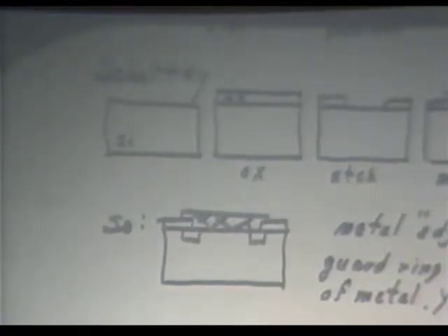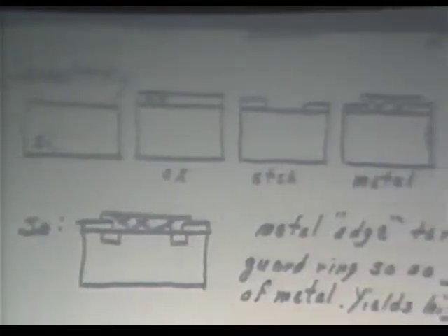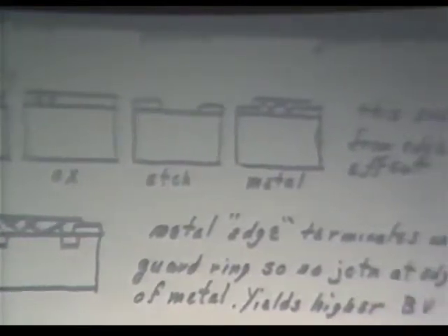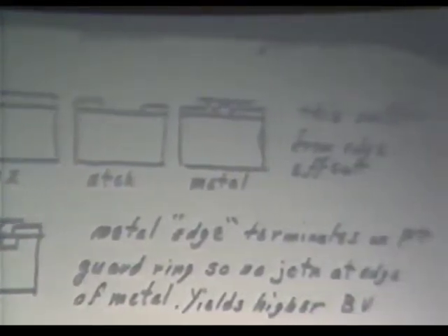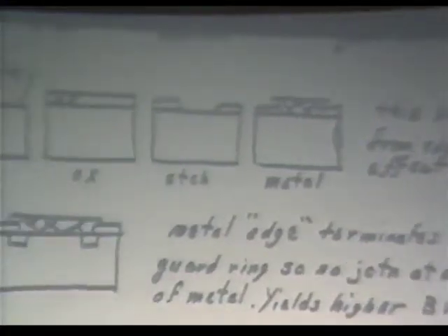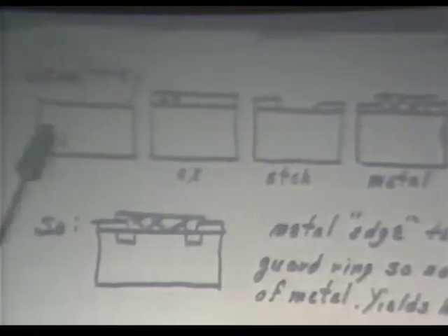When the people find out that to get a 7/10 volt forward at 10 amps, they have to accept 50 milliamps leakage at 20 volts, they go away. So far, that's what they look like. They have a nice low forward, but they leak like a sieve in the reverse. At any rate,